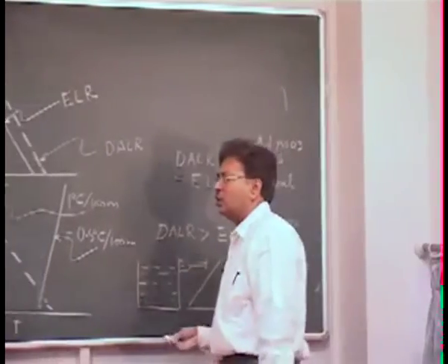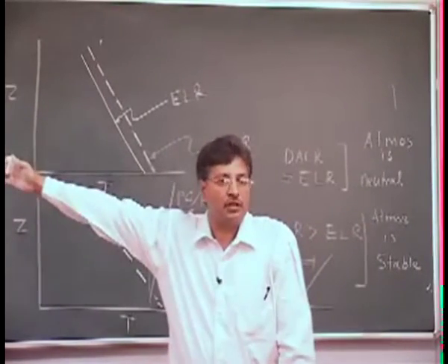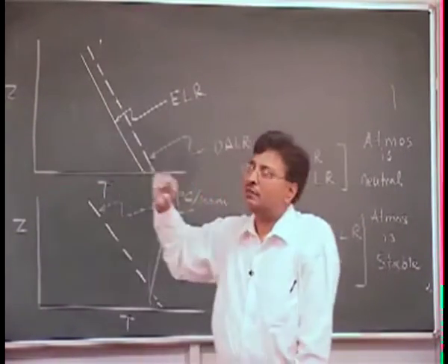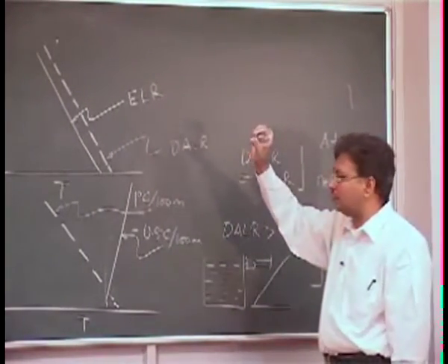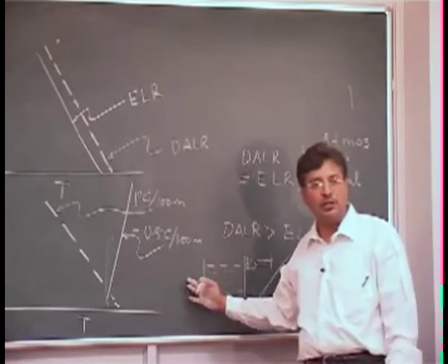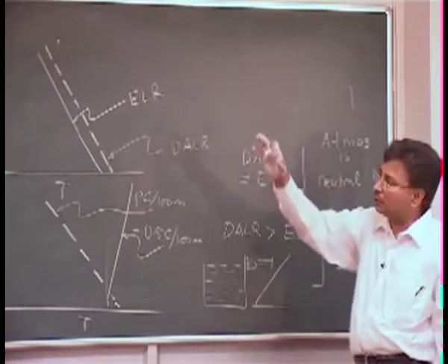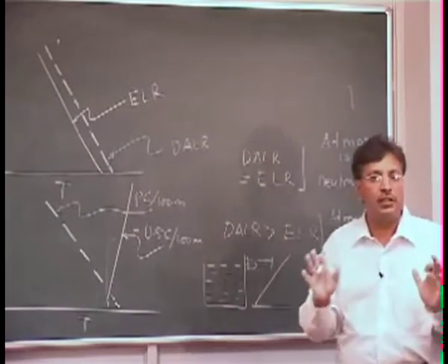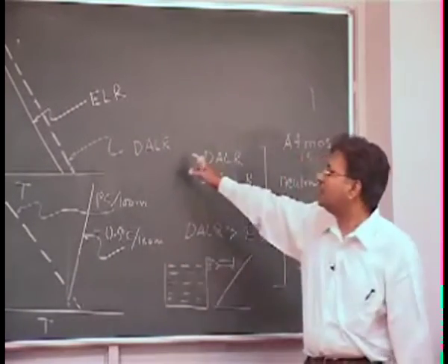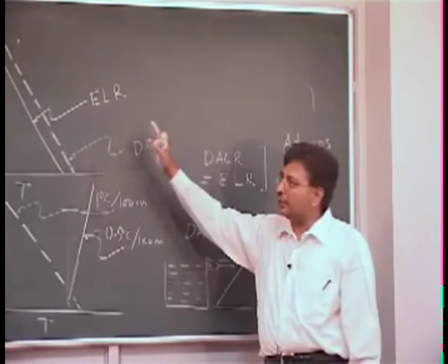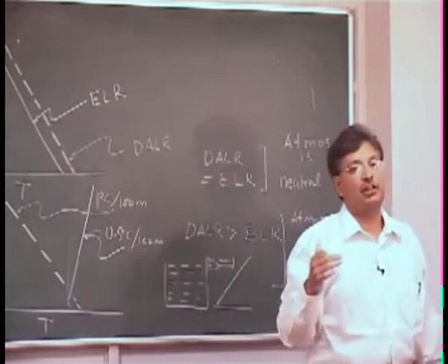Suppose I ask you, the plume is dancing, going up and down, and there is huge turbulence, what is the situation? Your situation there. When I say the plume is just not moving, it's just like a trickle, a small thing traveling, this situation is like this. It means there is no turbulence at all, things just tend to move, there is no vertical movement, especially as our lecture is focused on the vertical movement of pollutants. And then here there will be reasonable movement. With respect to these things, we can define the behavior of the atmosphere.